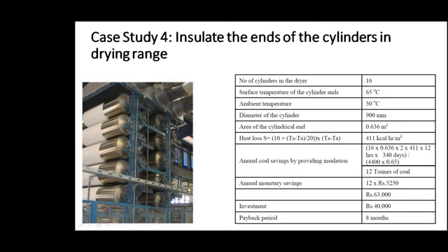So steam consumption can be reduced by 30 to 40% by optimizing the utilization of this width. So one cloth, you put two cloths here. That means the entire thing is covered, and with marginally more steam consumption, you get one more batch also dried up.